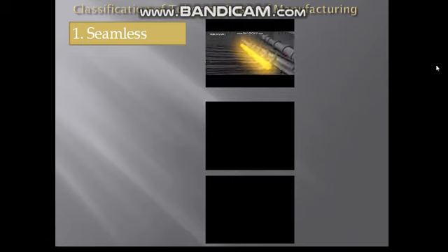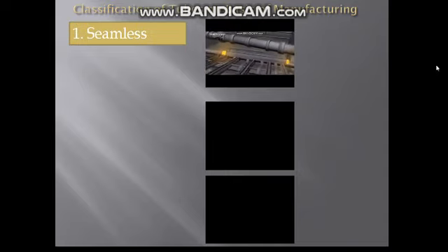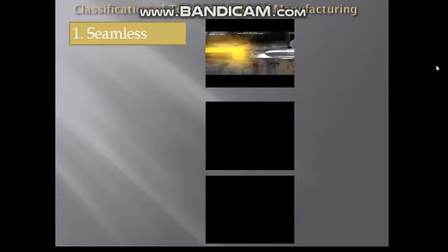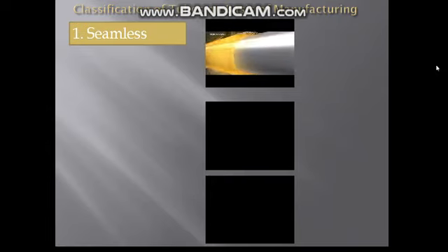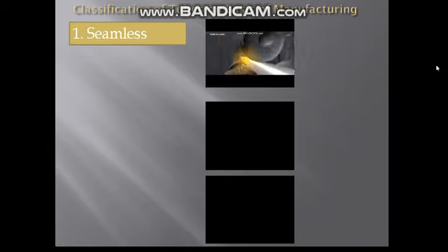To straighten this tube, tubes are again passed through number of rolling die. After tube is straightened, tube can be used as it is. But to enhance its property, it is again passed through number of processes. First process is pickling process. In this process, tubes are stored in an acid container to remove their metal oxides.